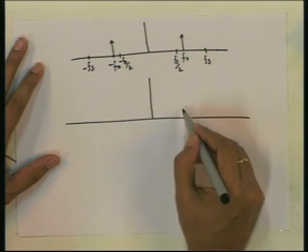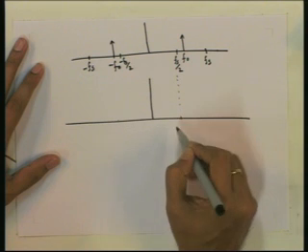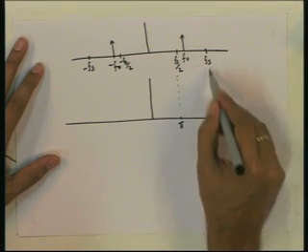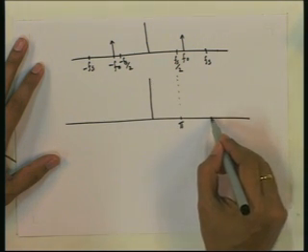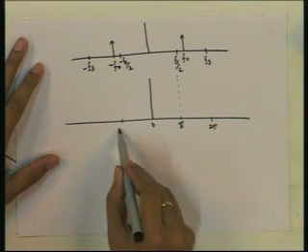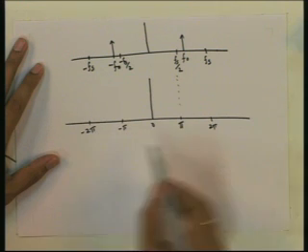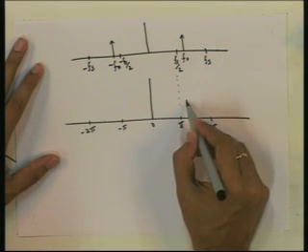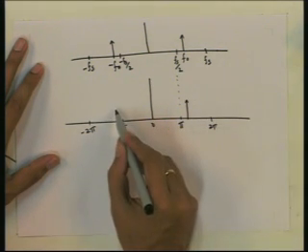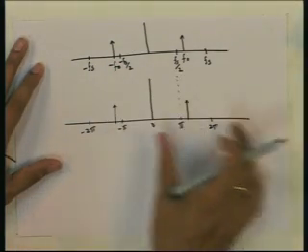So, the spectrum will be, so this Fs by 2 will be mapped to angular frequency pi, Fs will be mapped to 2 pi, this is 0, this is minus pi, this is minus 2 pi. So, we have one copy here, the original spectrum, then this will be shifted to 2 pi.